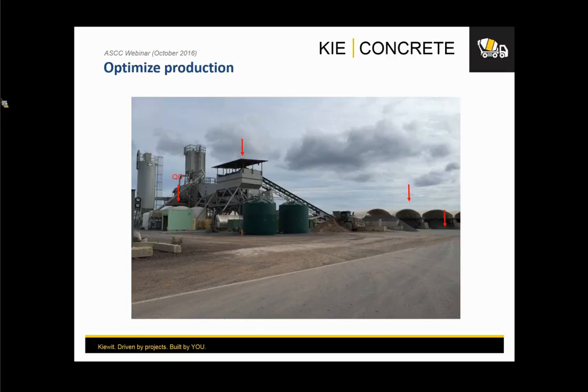The first one is you want to make sure you have an area for QC, right? You want to make sure that you are capable of evaluating the material properties every so often, check on your aggregate gradations, check on your slumps and airs, and check that you can cast some cylinders and put them in a curing bath while you're producing concrete. But there's some other interesting things here, right?